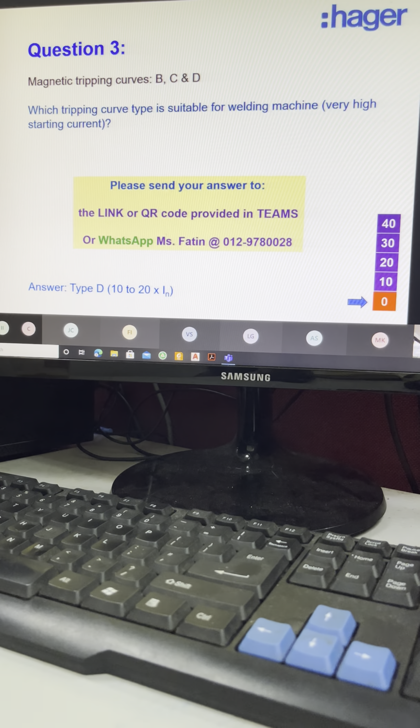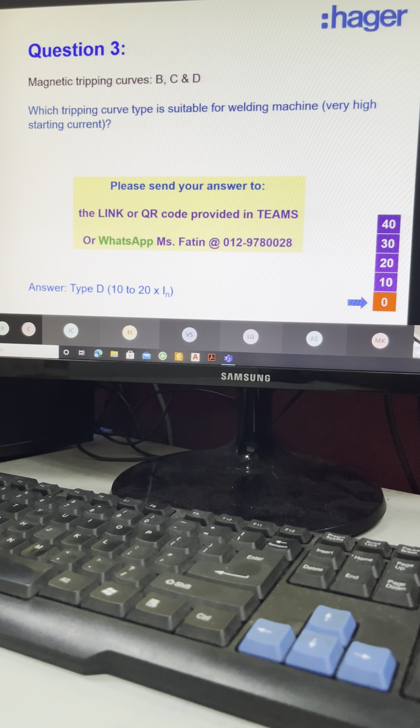Do not upgrade your breaker rated current unless you know the maximum cable carrying capacity. Some people use 2.5 square mm cable but use a 25 or 32 amps breaker. The reason, they say, is every time you switch on, it trips. So this is a very, very wrong way of doing things. Very unprofessional, and this is very dangerous.